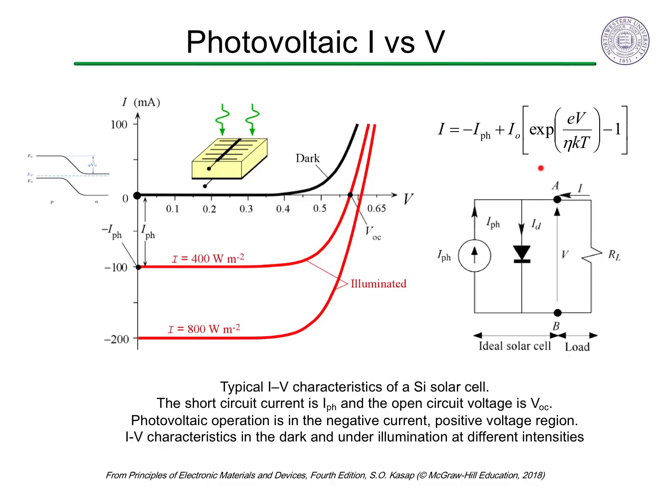The equivalent circuit of this description is an ideal current source given by the photoinduced current in the reverse direction along with a diode. The equation for the external current I with an external voltage V is given by the diode equation minus the photoinduced current. The IV curve of an illuminated photovoltaic looks like the diode IV curve shifted down by the photoinduced current.